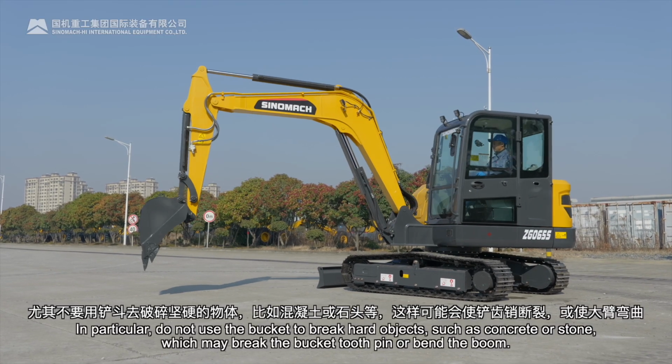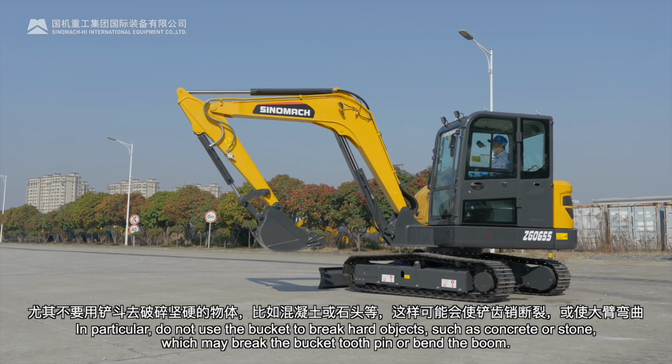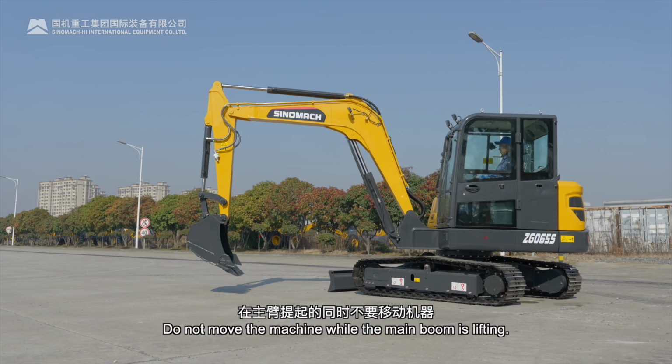In particular, do not use the bucket to break hard objects such as concrete or stone, which may break the bucket tooth pin or bend the boom. Do not move the machine while the main boom is lifting.